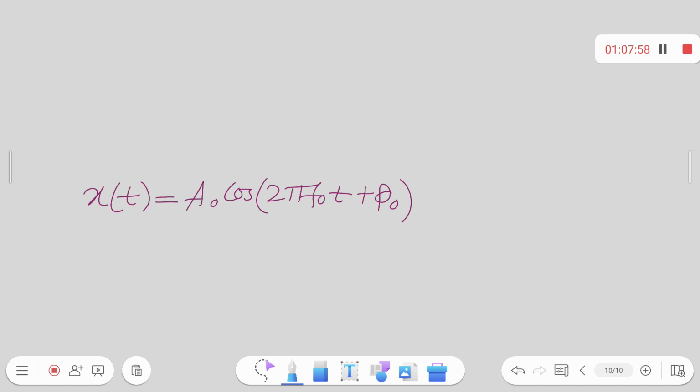However, there are certain signals for which you cannot, at any particular time, deterministically calculate the exact value of the signal. And these signals are not a single signal, they form an ensemble. As a whole, they will give you certain characteristics of their set. And these types of signals are known as random signals.